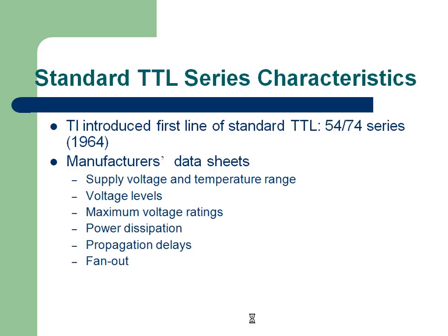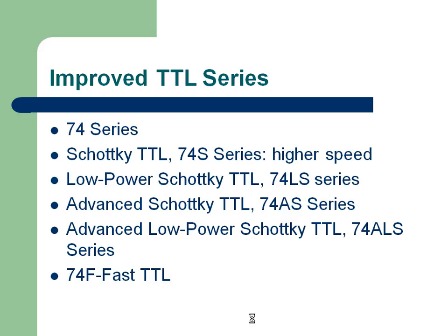This is all 1964 terminology. Nobody does it like that today. Today we go to FPGA, which is going to have millions of gates that you can configure. But anyhow, even though we are not going to use TTL for the logic inside the IC, for interfacing, that is one IC driving another IC, TTL is one of the standards.